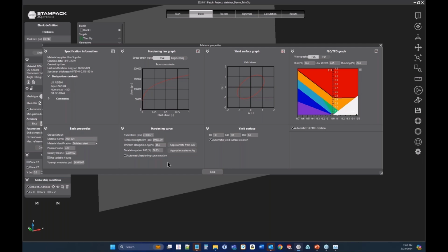Next question is, does the software work well for deep draw operations, and can it simulate breakaway on trimming operations? So deep draw and breakaway on trimming. It's exceptional for deep drawn parts. As far as the break, it does not calculate the break in the thickness of the part. But for deep draw, as Luca says, it's home game. It's really well suited to ironing and the thinning that goes on in a deep drawn part. That's one of the biggest pluses with Solid.